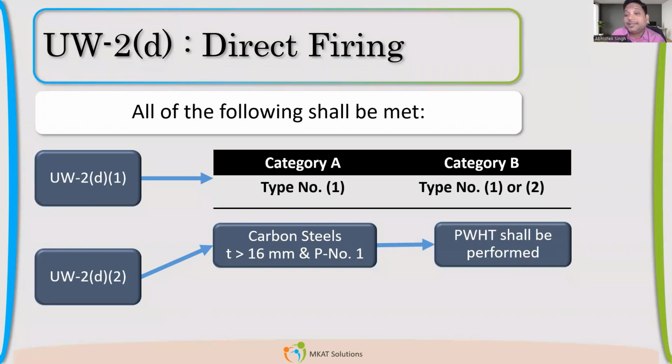But if it is a direct firing vessel which we are designing, in that case, if it is more than 16 mm, we have to do post-weld heat treatment.